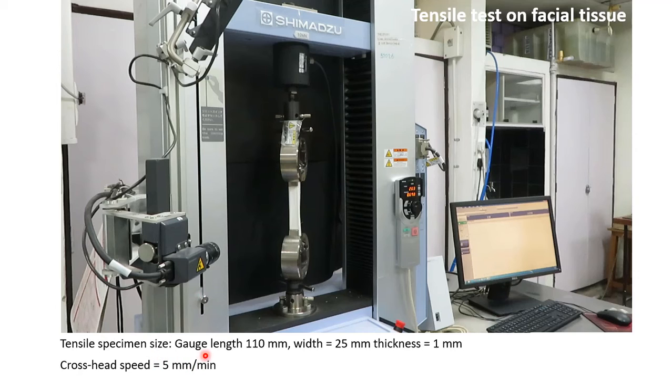The specimen size was kept at a gauge length of 110 mm, width of 25 mm, and thickness of 1 mm. And the cross head speed of this equipment was kept at 5 mm per minute. So we have conducted the test under these conditions. First I will show you just by hand how we can see the difference in the mechanical property of facial tissue in different directions.